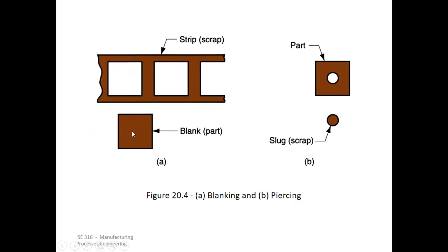This is called blanking because we require this. But this same blank part, again it was punched, and here this becomes your desired output now. If this is what we want, a sheet of metal with a circular hole in the center, then we have to make a hole. After this process, once this is removed, this goes here. If you want to remove this material, you have to scrap it out or use a punch.